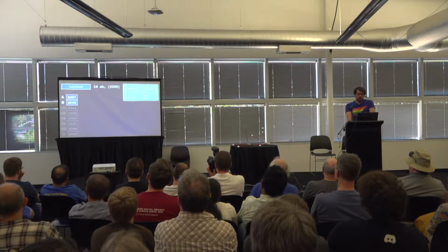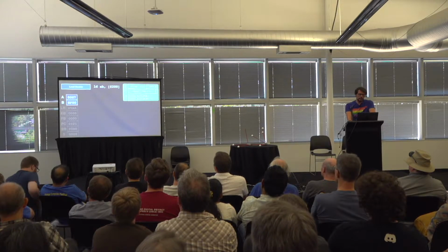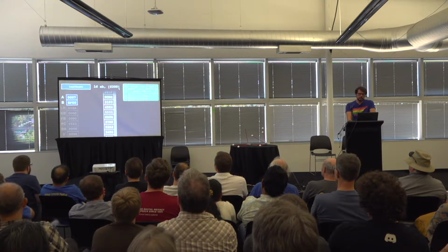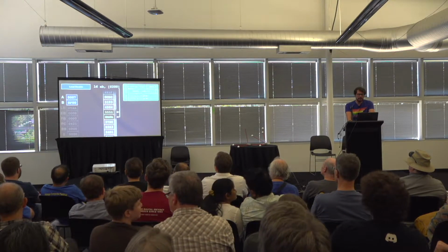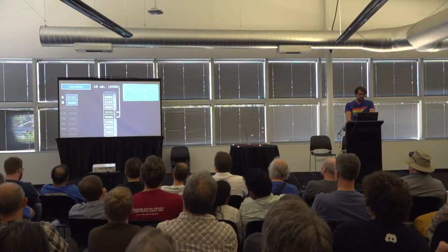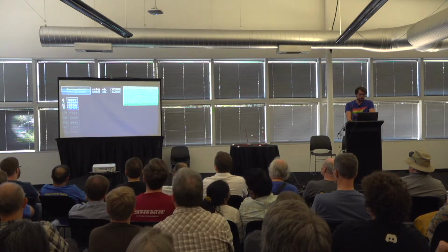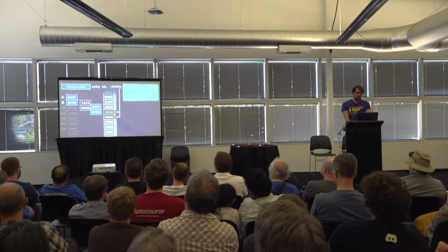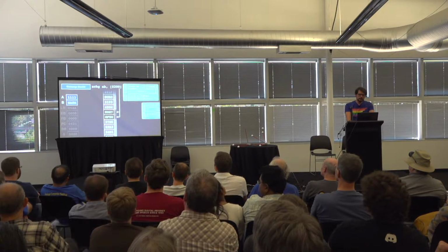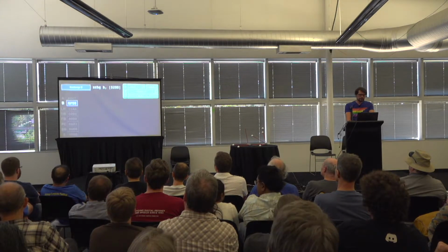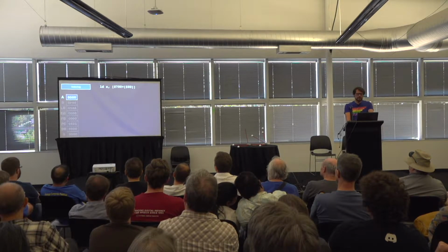Some other instructions also allow using A and B as a double word register. Load A, comma, indirect 200 looks up address 200 in memory and reads the words at this and the next cell into A and B. The load complement variant does the same, but inverts all bits during the load. There's no instruction to store A and B in a single step, but there's a double word exchange instruction. And finally, there's an add instruction that works in double words. And to load and store just the B register, there's an exchange instruction for that.